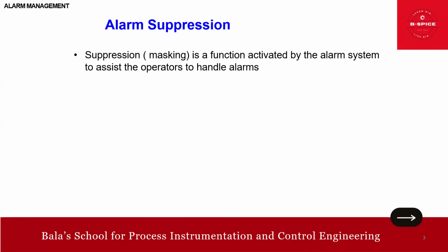Suppression techniques result in alarm signals from equipment being assessed as not appropriate for display to the operator. So that is the point. They can be very valuable, but should be applied with care. That is also what we need to focus on. Safety problems have arisen from inappropriate use of suppression. So if we don't do it properly, then that will also backfire. In some cases, use of suppression may be designed to reduce the alarm priority rather than eliminating the alarm altogether. Whatever approach we are taking, suppressed alarms should still be recorded as events. That is the summary I want to put forth.